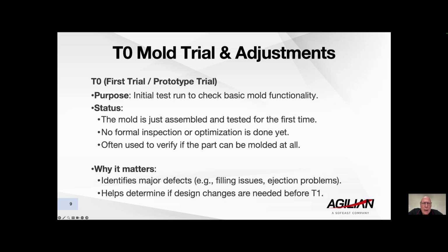If everything's working out okay, we should see exactly what that mold flow result gave us. In other words, where the weld lines are, where the cold fronts, hot fronts, where there's any short shots showing or anything like this. This is really important because it allows us to see any major defects before we move forward into the first trial. This allows us to give the time and effort to actually fix anything that is causing us issues.